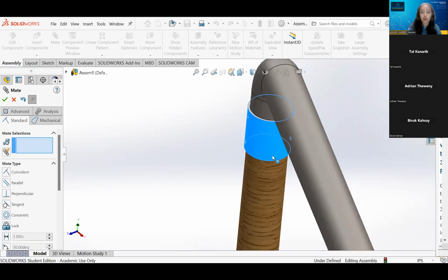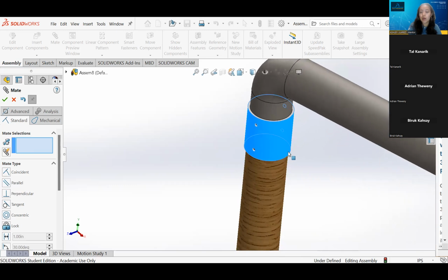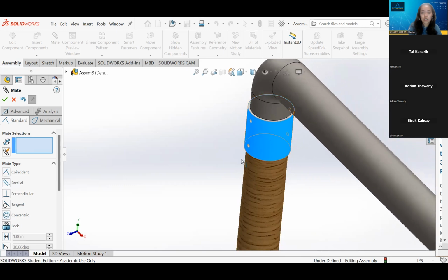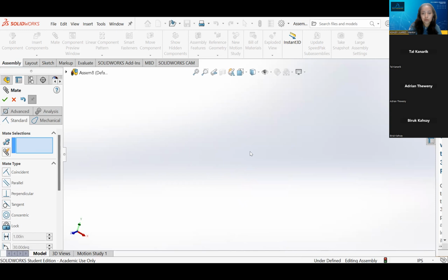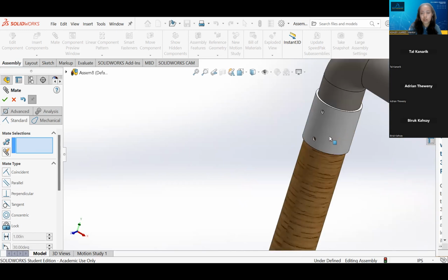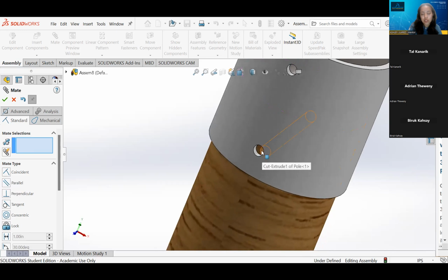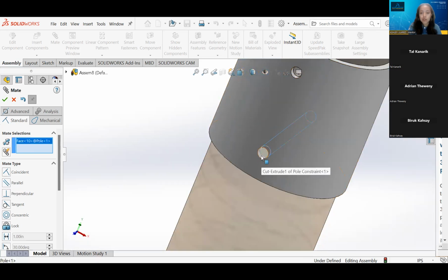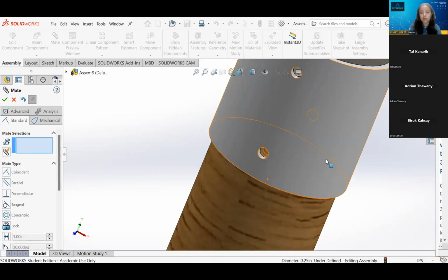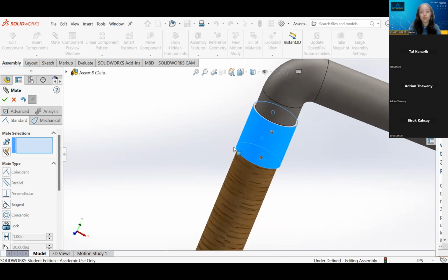And this still moves. Why does it still move? Because I didn't make the bottom part concentric. So I'm gonna make that as well. Oh, I disappeared. So I'm gonna select this inside face here. It's a little hard to see, but for that reason, you can move your parts, right? Because they're not set in stone. I'm gonna select that. Same thing that I did at the top part. And I'm gonna make it concentric. Boom, now it won't move.